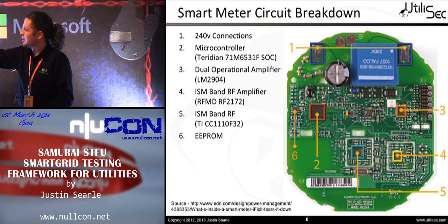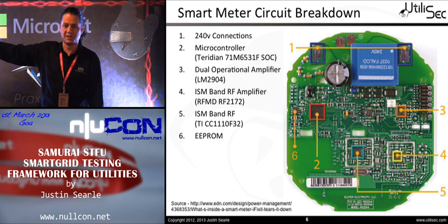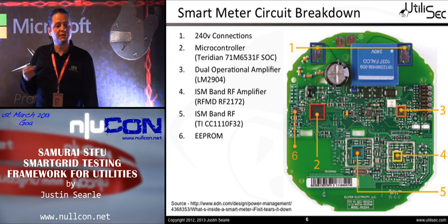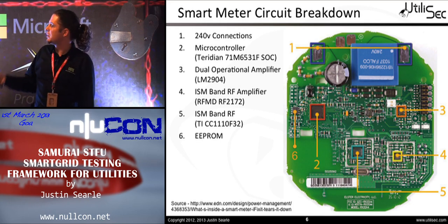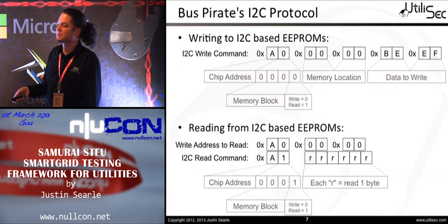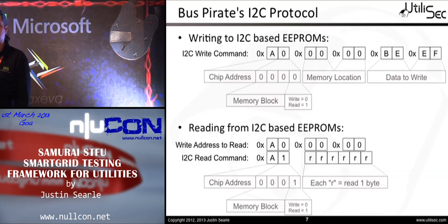So we worry about having tools that help us talk to the microcontroller that's on this board. Different types of JTAG tools allow you to talk to that microcontroller. Also tools to talk to the individual chips themselves and to speak the serial protocols that the integrated circuits speak, like I2C and SPI.